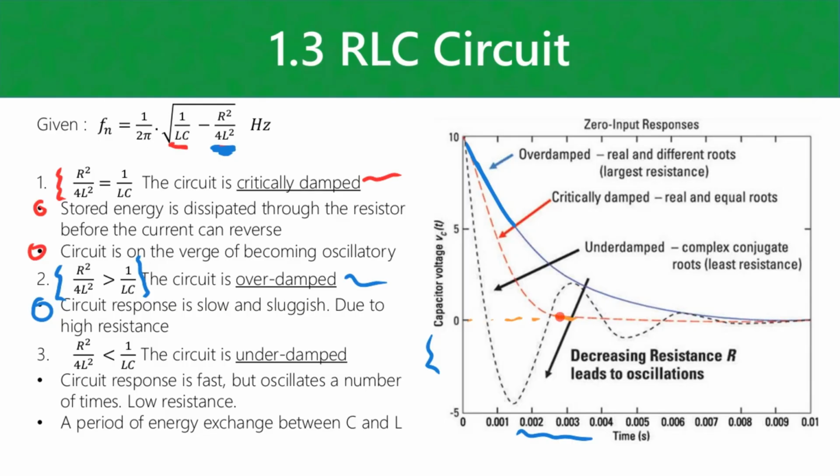I have a step change from 10 volts down to 0 volts, and this is the response of your circuit that we're measuring here. The response can be the other way around as well. You can have a step change from, let's say, 0 to 5 volts, but then the oscillation and settling point will be around 5 volts. Just to explain that real quick.